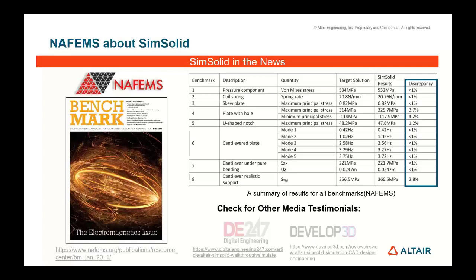Now, if you're interested in a single weld, so only looking at the detail of the weld and how the stresses and strains inside the material or in the volume will decrease or increase, at that level of detail, you should then again probably use a meshed model of a cutout of the whole geometry. And the advantage of SimSolid is that the larger your structure is, the faster it is compared to classical meshing. Yes, you're absolutely right. And the more detail you need, then you should probably go to classic meshing.